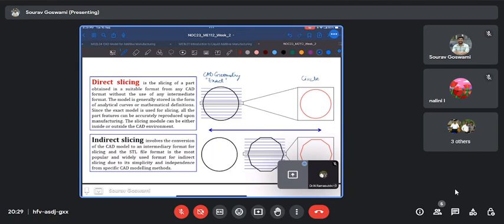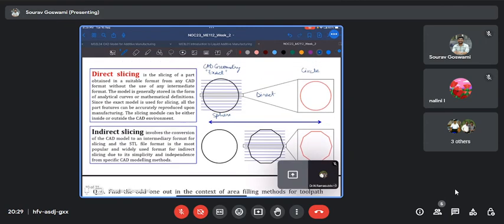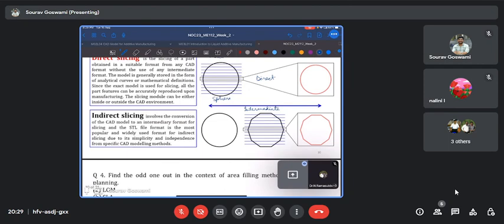So in the slicing of an exact sphere, we'll obtain exact circles in each contour. So this is called direct slicing. Whereas in indirect slicing, again, we start with an exact CAD geometry, but we have this intermediate step where we actually approximate that exact geometry by tessellation into an STL file. And we are well aware that this STL file is approximate. It gives us a good representation of the complex surface, but it is not exact.